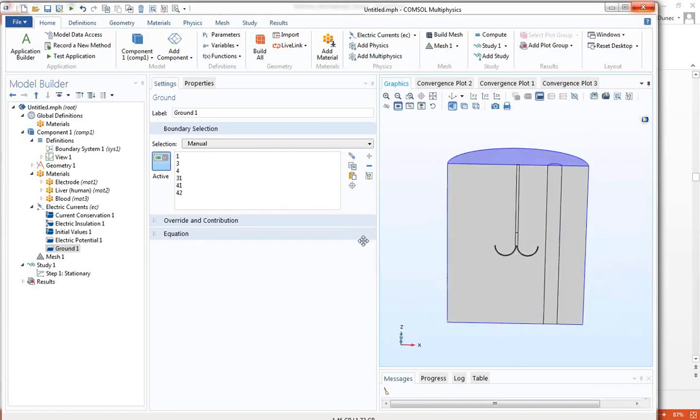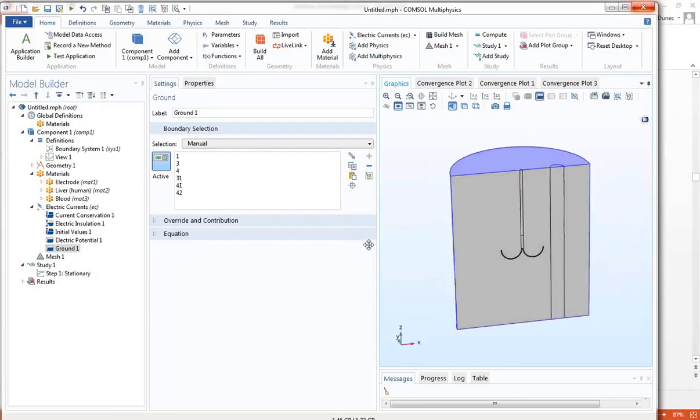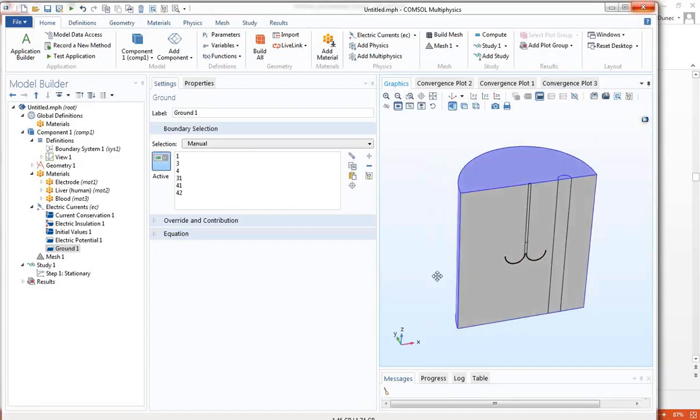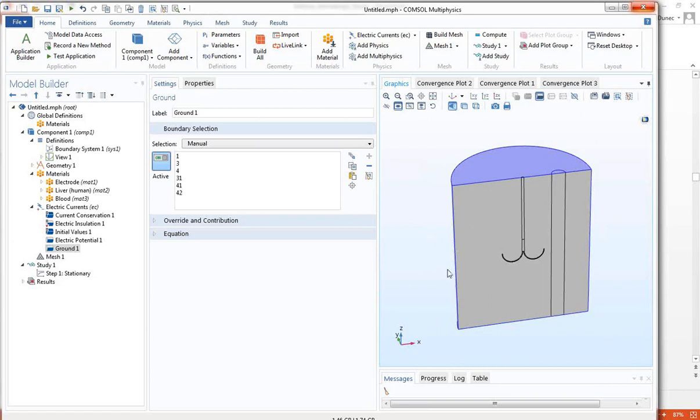Now, at this point, this is where the engineer in me starts getting really nervous, because we have a voltage here and we have a ground here, and I'm really nervous whether or not I've distorted the field. Has that gone down too quickly to ground? Because literally, I can drag this boundary in and sort of dial a solution. I squeeze that in, and all of a sudden the gradients go up. So in doing this problem like this, I have made a choice, and I want to change that.